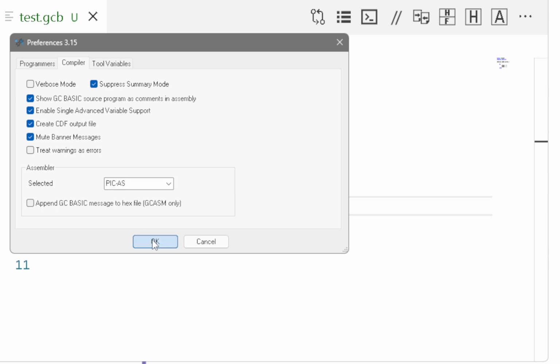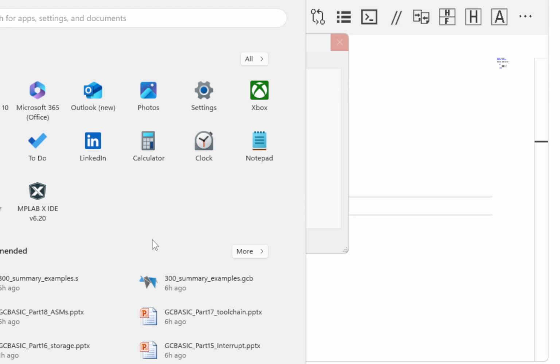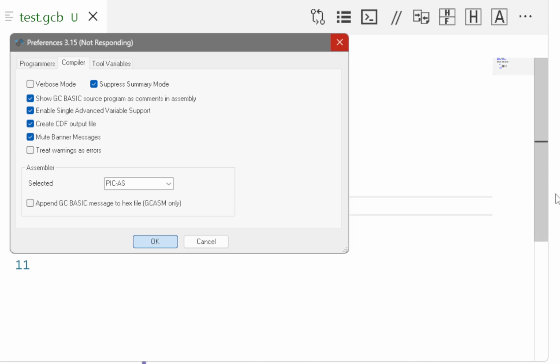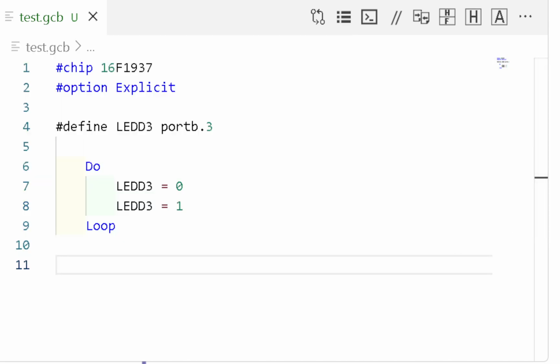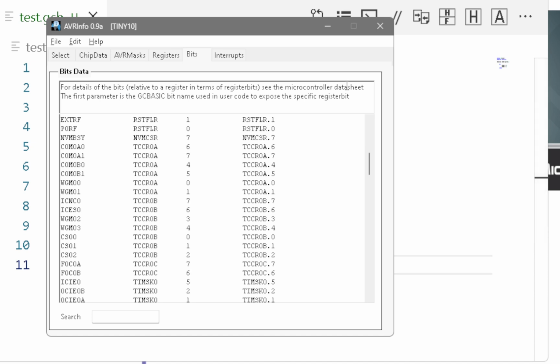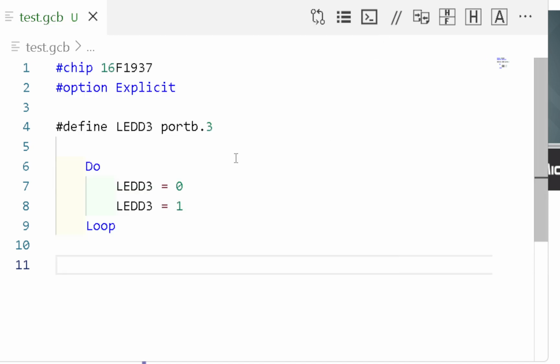And that's a functional change to the output on the compiler. It will still generate what's called an ASM file, but now it will produce a suitable file for MPLAB-X. And whilst we're waiting, I'm going to fire up MPLAB by clicking that icon there. I'm doing that now because it takes a few seconds to open. Okay. Now, here's my program, and in the back you can see MPLAB opening. That's great. Not a problem.